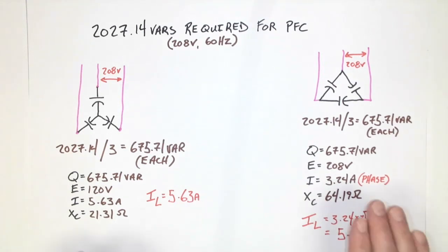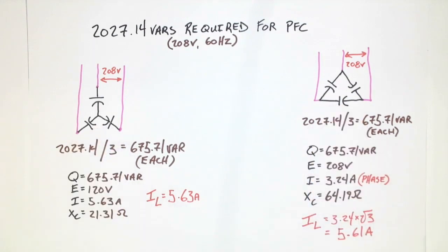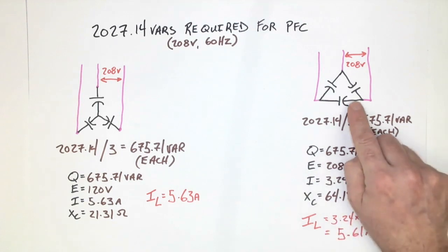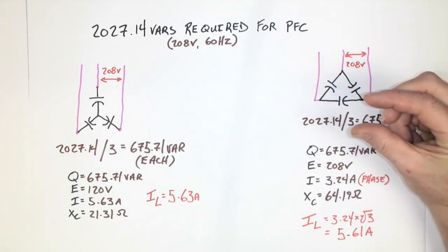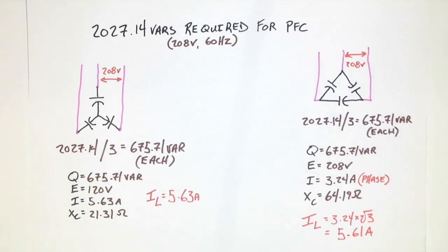And when we're looking at the difference between these two capacitors, the capacitor that has to carry the most current will be the most expensive, because the only way we can account for more current is to make the innards more beefy with more copper in order to handle the current. Whereas voltage is much easier to accommodate simply by expanding the spaces between the conductive metal components inside a piece of equipment.